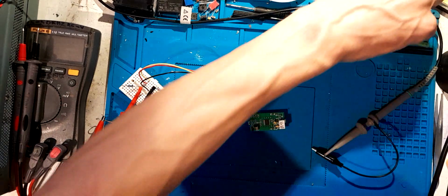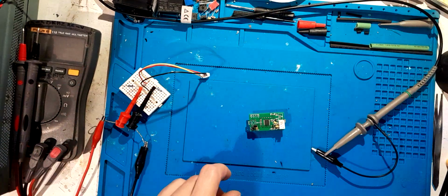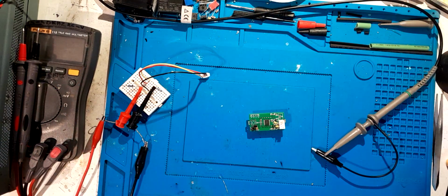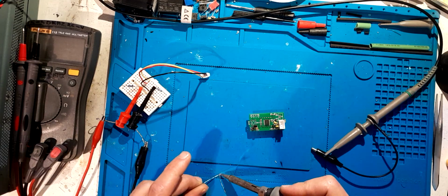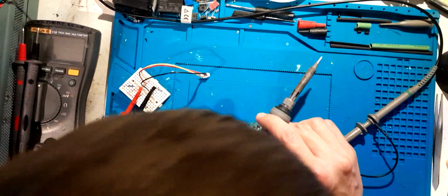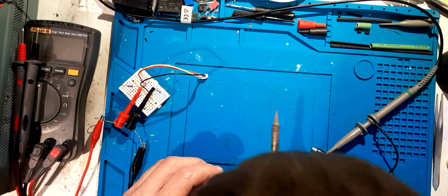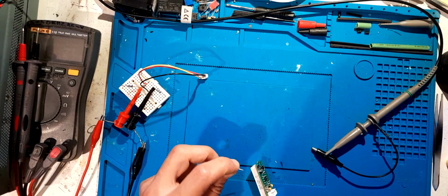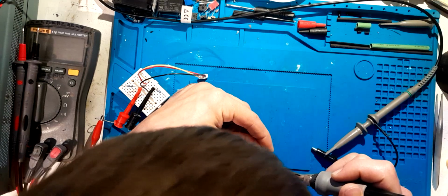I'll just do that using a piece of scrap resistor lead. I got copper wire too, but it's expensive using tin copper wire, and it's thicker too. I don't need that thickness for this short little run of something that has maybe 10 or 20 milliamp peaks on it in the worst possible case scenario.